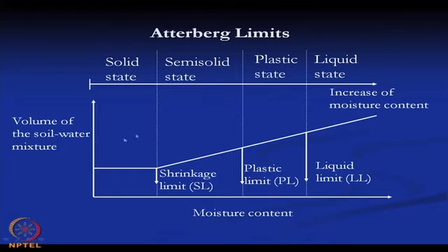Now, if I draw a graph of moisture content versus volume of the soil water mixture, we can see that if we decrease the water content, then from the liquid state it will go to the plastic state and then to the semi solid state, and as we reduce the water content, the volume of the soil water mixture will also reduce.